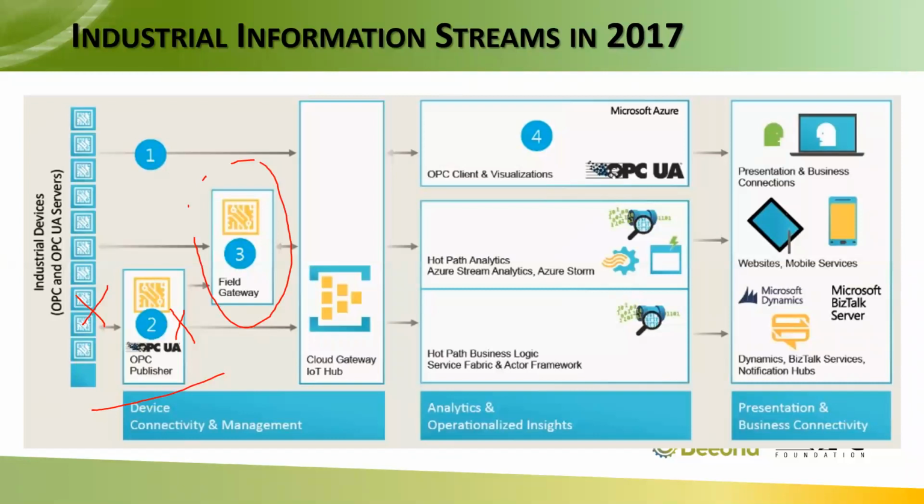Yes. And let me just take that back. So logic and calculation are taken at this level. They are somewhat aggregated as an OPC UA server level, but they are coordinated by a gateway. So these gateways are the field gateways. There are on-site services that run, and they make sure that the communication with the OPC UA servers is healthy, ongoing, and if it's failing, it can fall back to some other nodes.